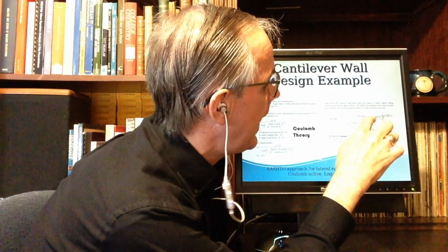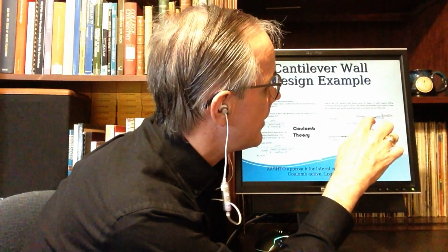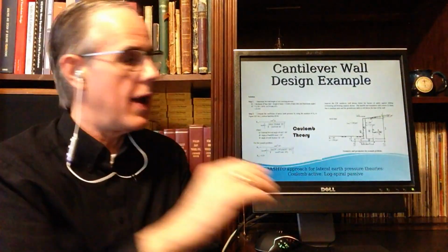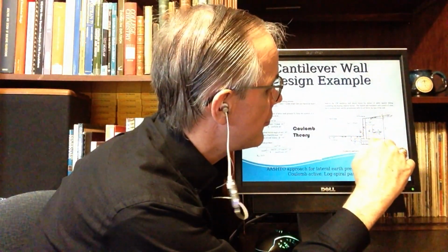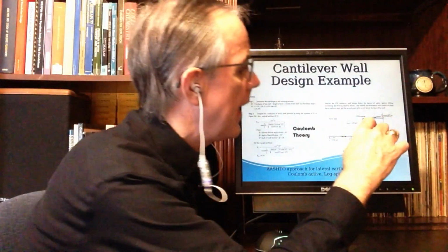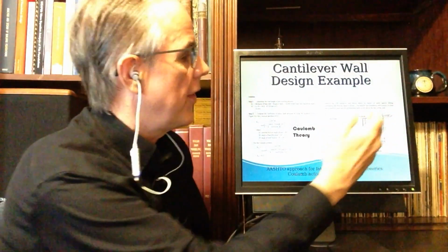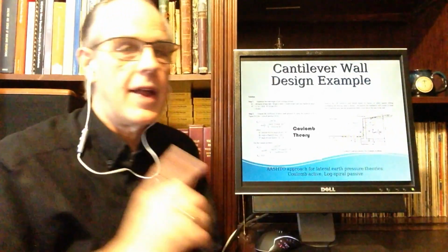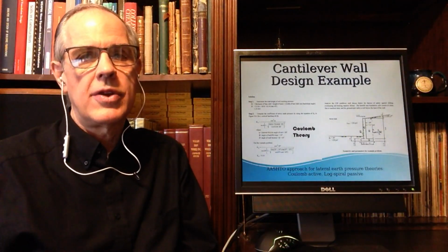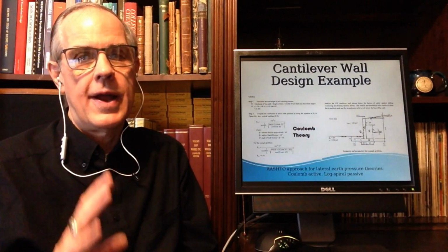And so we have to add the distance from here, where it's the top of the wall, to where it's at the top of the soil at that point. This is at the point directly straight up from the heel to the surface of the soil. You have to add this; this is the total distance of the soil acting. That's the distance of the X. That's the really big downside to using a cantilever wall, the soil behind a cantilever wall.